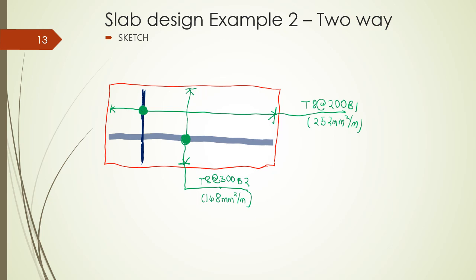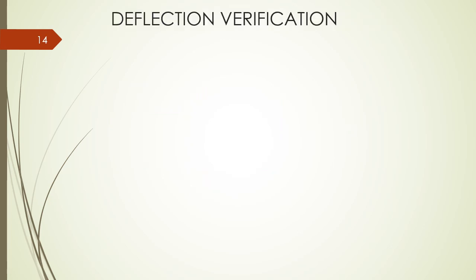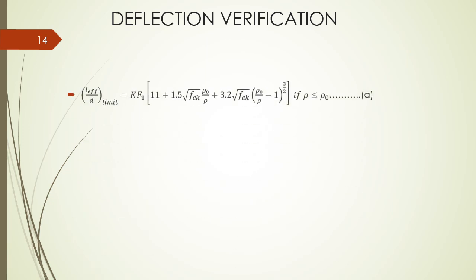This will be the sketch from your calculations, which will be used by the detailer to make the detailed structural drawing. So after this, we need to do ideally other additional checks. We could do shear, but that's not usually critical in the design of slabs.